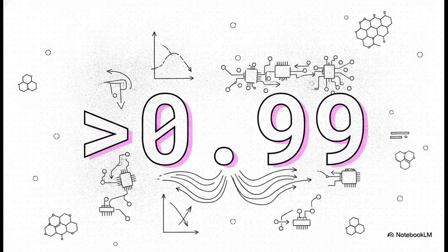Thanks to nanotechnology shrinking that base thickness down so it's much, much smaller than the diffusion length, modern BJTs can achieve a base transport factor over 0.99. That means 99% of carriers are surviving the obstacle course. It's a truly incredible triumph of manipulating Fick's original laws.